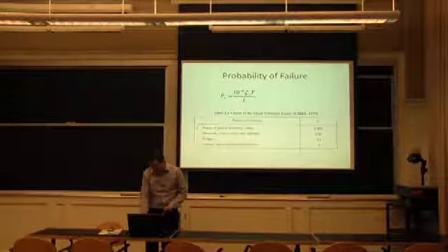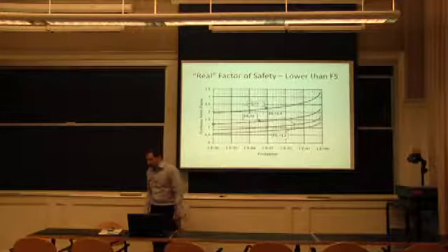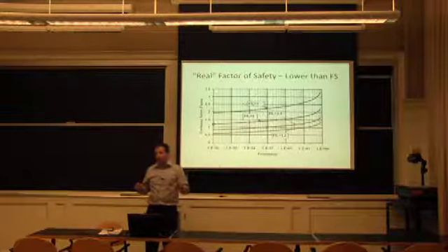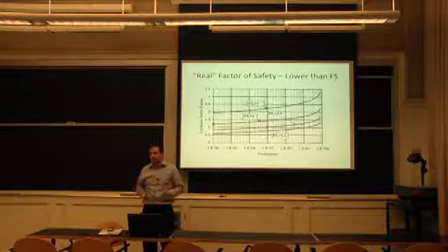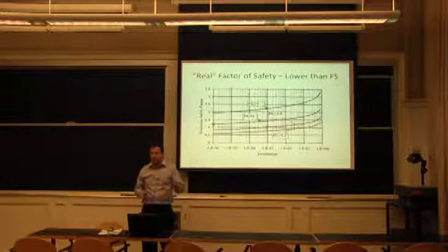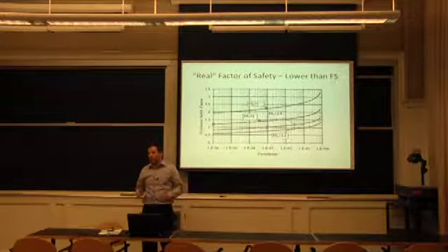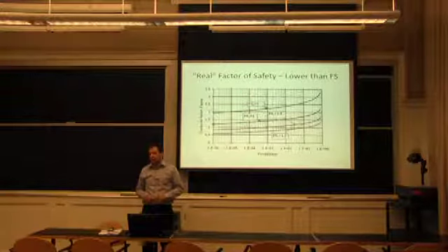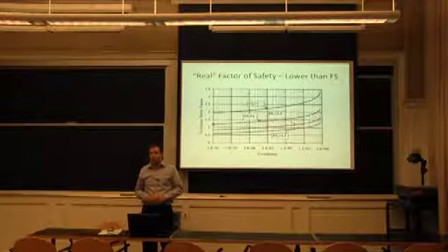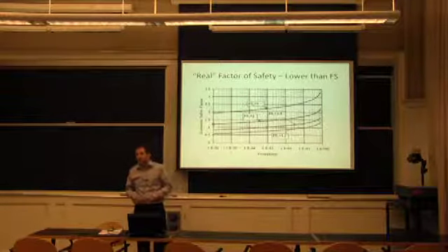The probability of failure, we touched on that again at the beginning, that there would be a different safety factor or a final acceptable safety factor for different types of structures. So I'm not going to rule that out. We can't say we're over-designing everything by 20%. It's not true. It will vary depending on how willing you are to risk a failure. And we had that popular shaft example that was designed to fail within 400 hours. And therefore, the safety factor for a 10-year life is less than 1. It's just the way it is.